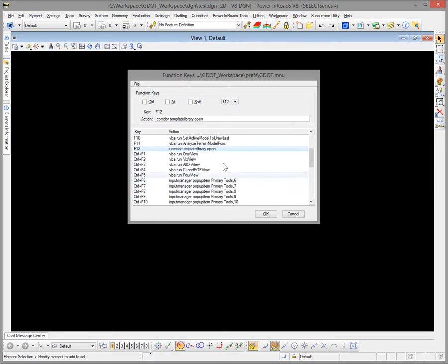The other one that was modified, you can see here we have some Control F1 through Control F5. I don't use these very often, but they will set up particular settings within the view. You can take a look at those. And then the Shift F1 is something that you want to provide for the surveyors, especially where it can exaggerate the Z elevation, basically distort in the Z a referenced-in empty model. So it can take your existing terrain, reference that into a dummy model, stretch the Z so that they can find problem areas in their survey and see those more visually.